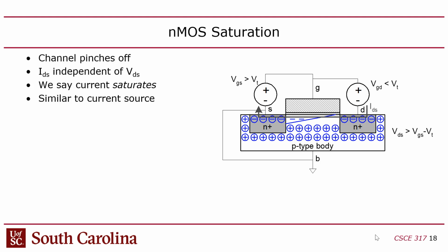What ends up happening, and I always find this interesting. So I mentioned that when the transistor's on, the channel becomes decoupled. You have to look at the average voltage across the channel, right? As long as the source and drain are about the same voltage, then the gate source voltage is going to be about the same as the gate drain voltage, meaning the voltage between the gate and the channel is about the same all the way across the channel.